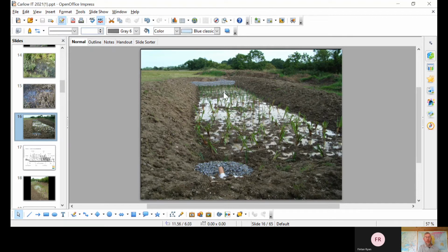So what we've done is we've taken the natural treatment mechanisms and we've maximised their potential for treating the water within the wetland basin. This is the planted water depth. Full operating depth will be about 4 inches. So it'll be a bit deeper than that, maybe 4 inches deeper than what you see there, so that when the plants become established, it'll provide that volume of water. So there's a residence time within the basin as well as everything else.